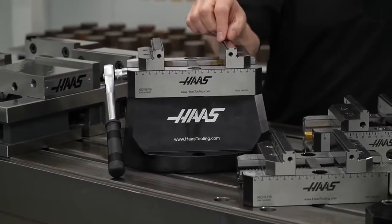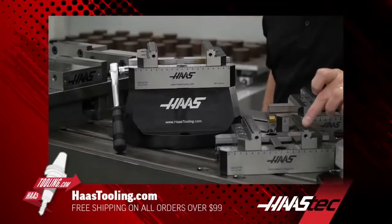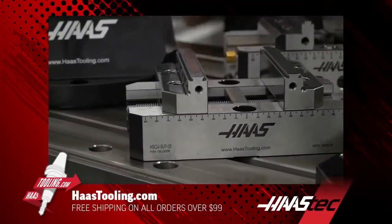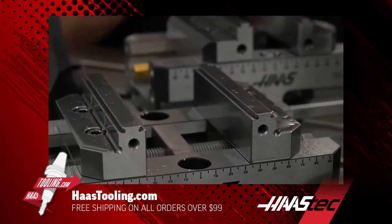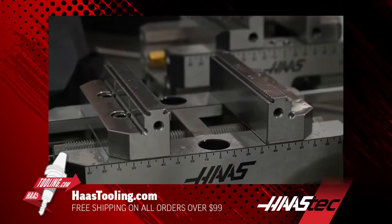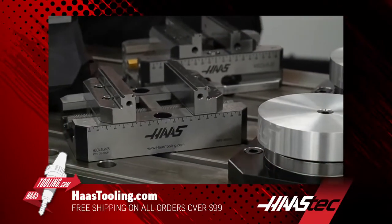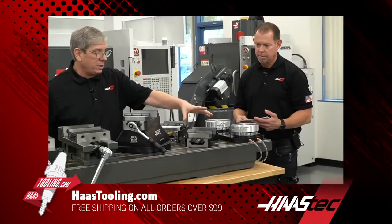The jaws are serrated and dovetailed. If you can get a good close-up of this right here, you can see an example of the serration that will bite into material if you're holding on to the edges of material, or you can even put a 45-degree dovetail on the bottom of your part, 3mm or 1/8 thick, and this will hold it. I use this exact vise style on the VR8 demo that we saw earlier this week.